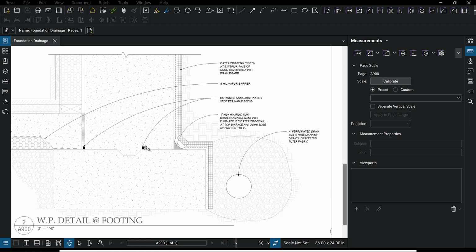I'm sorry, I said that wrong. It goes on top of the footing, and as you place the foundation, concrete gets cast all over the top of this, and then if any water does come in this way, it will expand and get into any kind of voids in the concrete and act as a water stop, is what it's called.